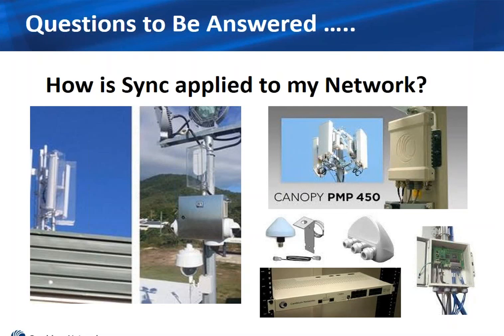The other examples I gave that build into this solution are having automatic transmit power control that works well, having good specifications on your antennas, your access point antennas that have very good front-to-back ratios, and there's big, strong reasons for that being needed. Duty cycles, having the ability to set your duty cycles, things like that.